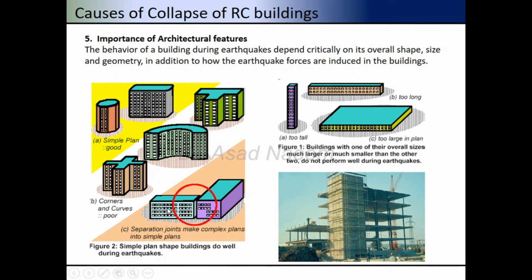We can see different kinds of building structures, and in this figure we can see the shear wall is being provided at one end. However, the other sides of the building structures have fewer columns. It can cause a torsion effect in a building structure.